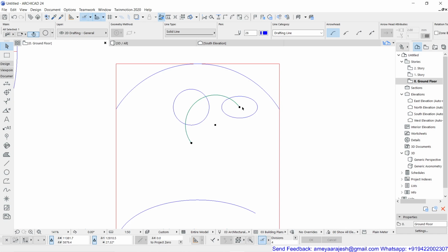And if I want to convert this arc back to circle, you know it very well. Click on the end node, and with the angular stretch, you continue and complete this circle. So this is altogether our journey: started from circle, then arc, then line, and from line back to arc and circle. So please complete this entire exercise and explore this, because in future when you start using the advanced tools like wall or slab and beam or shell and a number of other commands, you will realize the same editing techniques continue if you are going to construct that type of object. For example, a wall which is supposed to be curved, or a slab which is elliptical or circular. So you should know all these editing options very well so that you can survive there.